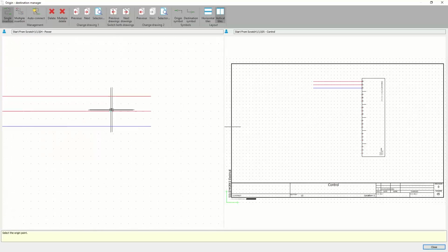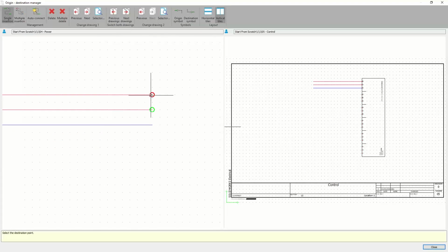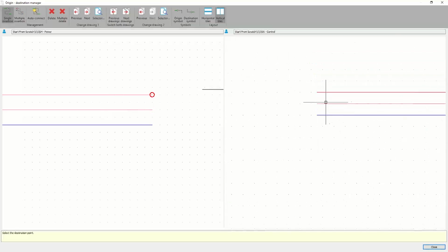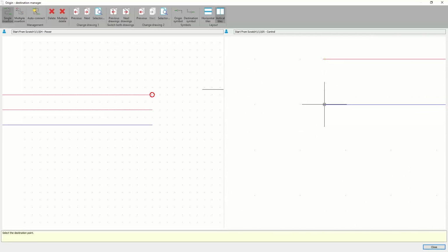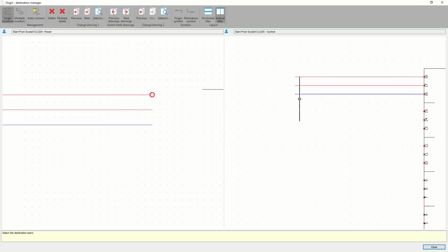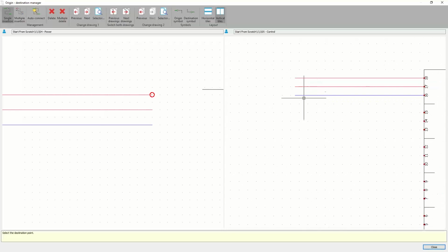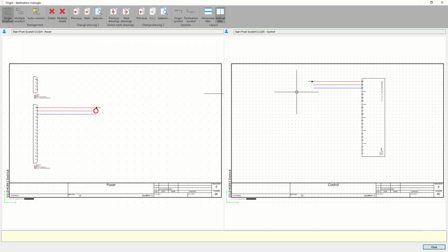And we notice as soon as I go to select this, it only allows me to select the same wire style. So if I zoom in really close and try to connect to this blue one, it does not let me do that because the properties, the information about this wire is not the same. So it's not going to let me connect to it, which is a nice little design rule check. If you're ever trying to race to get a project done, it kind of helps stop that from happening. So I'm going to go ahead and connect those two up like so.